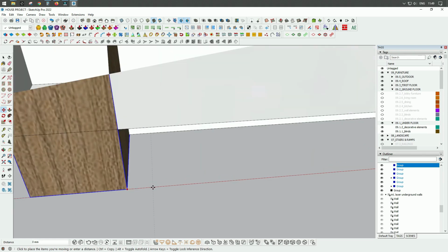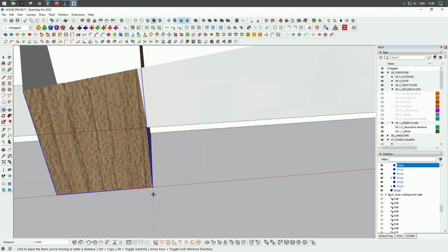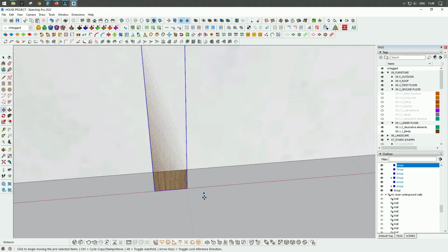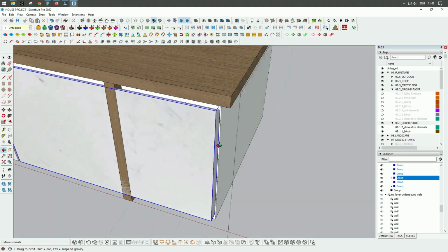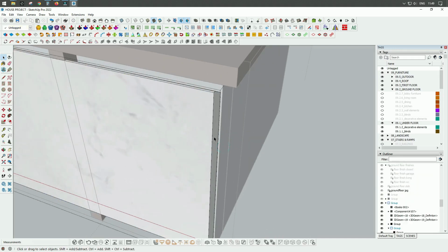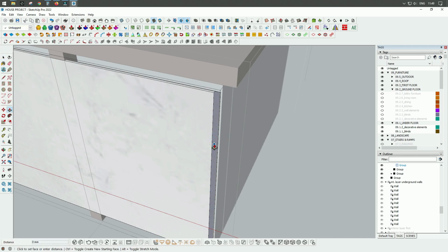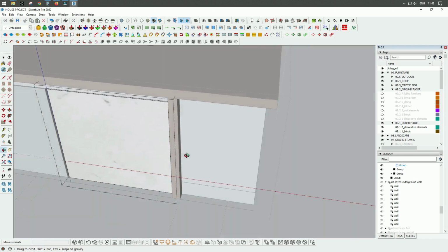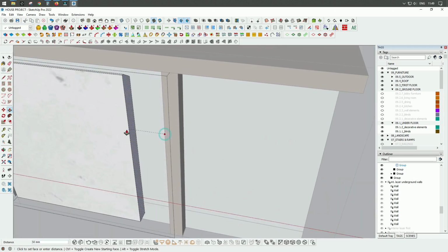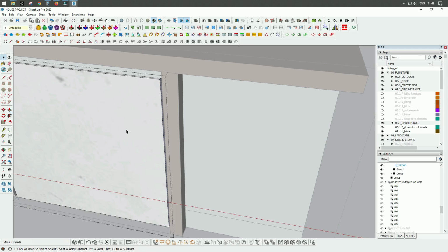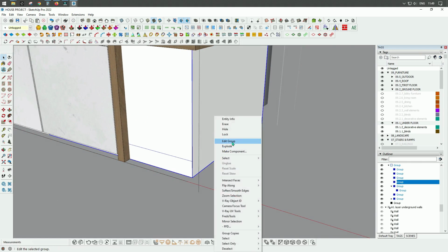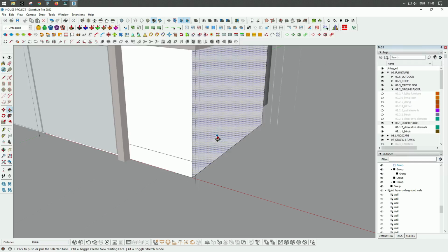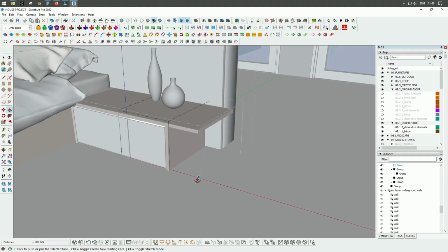I have to adjust exactly on this point here. Now I can go into this element here, edit group again, a lot of groups, but to the edge of our element, and from the edge 2 millimeters. And I will do the same with this face as well, up to this edge here.